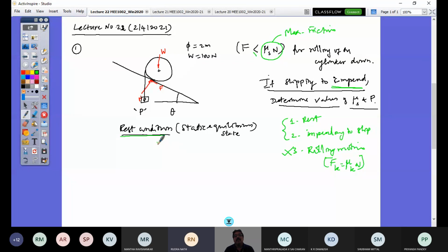They shouldn't be parallel. They should be concurrent. Three non-parallel forces, if they make a system, can be called a 3-force equilibrium. 3-force equilibrium is one of the fundamental concepts of statics. 3-force equilibrium means the 3 forces should essentially be concurrent.